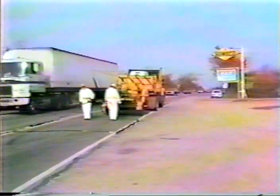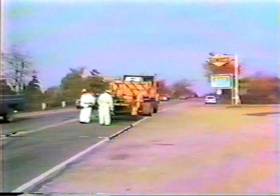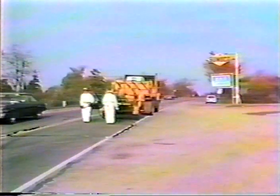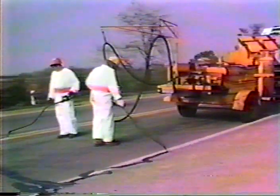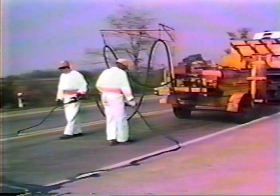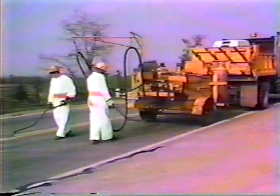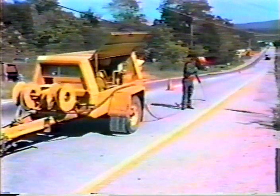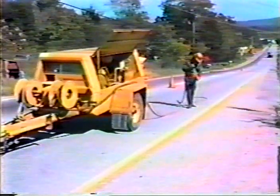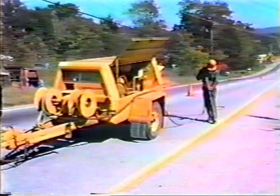Crack cleaning and sealing involves specialized equipment: an air compressor to clean the cracks, a heating kettle with a pump, wand, and thermostat and agitator, and sufficient equipment to transport the compressor and heating kettle. A hot lance may also be required. Compressed air is used to clean cracks. The air pressure should not exceed 30 pounds per square inch.